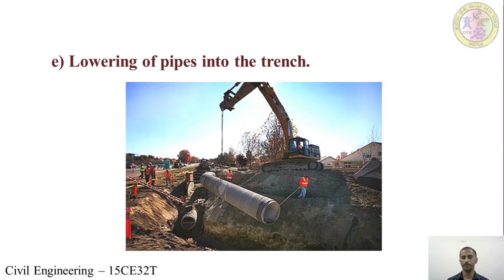Next step is lowering of pipes into the trench. The pipes are brought to the site and stacked, and before laying them into the trench, they are cleaned from any foreign materials and laid slowly such that the pipes may not get damaged.